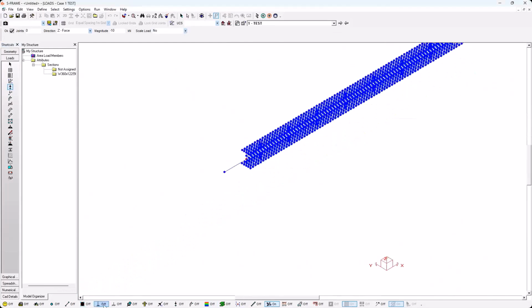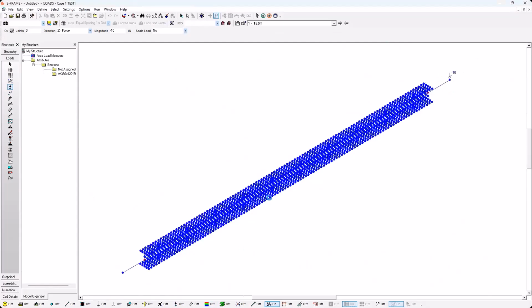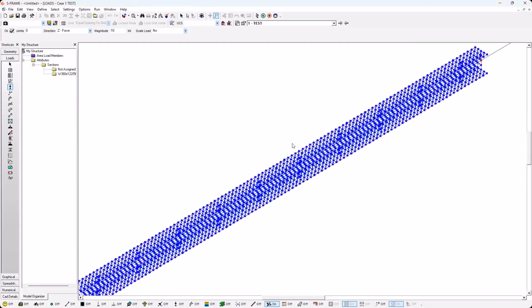And you'll see here that we have retained our joints at the end as well. Now, I could have just as easily extended the mesh to the entire length of the member, and I would have been able to then control, do I want just my webs supported or loaded? Do I want anything else to be controlled in a different way? We can also convert loads on members to loads on our shells. There's a utility to do that, and you can find more details on that in the help system. Unfortunately, we don't have time to go through every possible circumstance today.